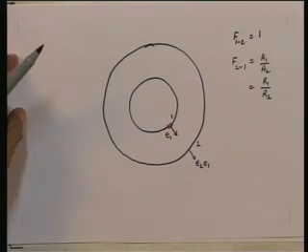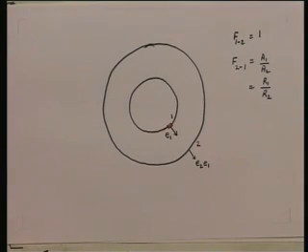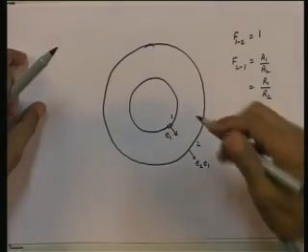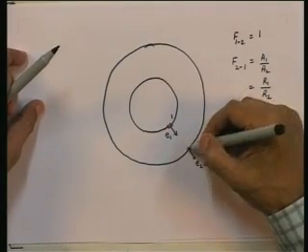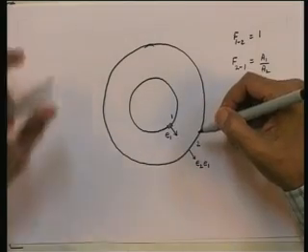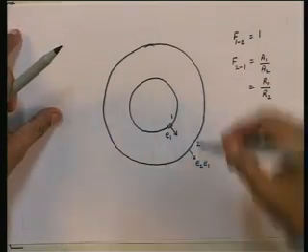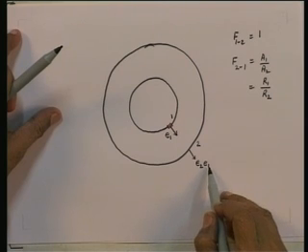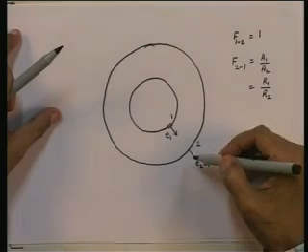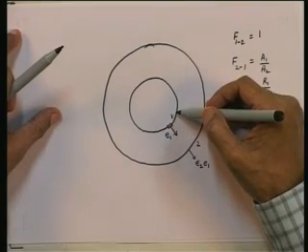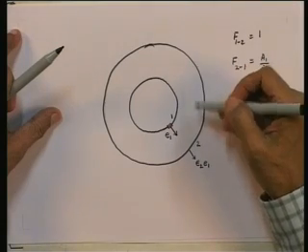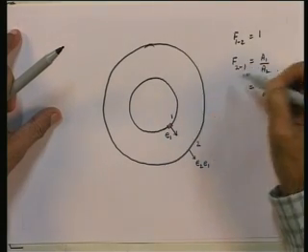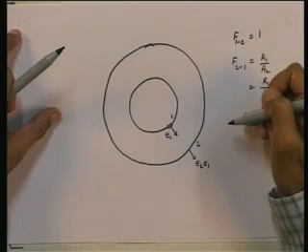So many watts per meter squared will be absorbed, and a certain amount will be reflected, all right, which will again be reflected in all directions like this. Out of this reflected amount, which will be 1 minus epsilon 2 into E1, a certain amount will go back to the surface 1 and a certain amount will go back straight to the surface 2, because the F2 to 1 is A1 upon A2.